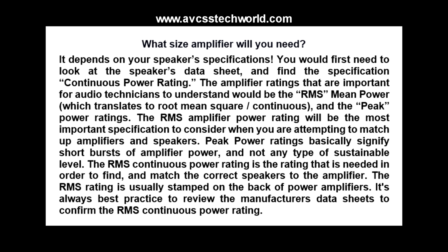What size amplifier will you need? It depends on your speaker's specifications. You would first need to look at the speaker's data sheet and find the specification continuous power rating. The amplifier ratings that are important for audio technicians to understand would be the RMS mean power, which translates to root mean square / continuous, and the peak power ratings.